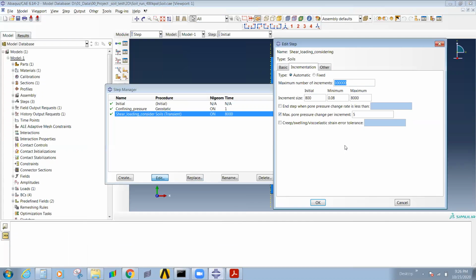It is like the number of elements is very less, so any calculations will be within a quick turnover, and you will get a solution. For any other problem, start from 100 or 50. If it is taking too large a time and your problem has not converged, you need to increase it. If your problem is solving early, then reduce this number of increments. Then it will be fine.